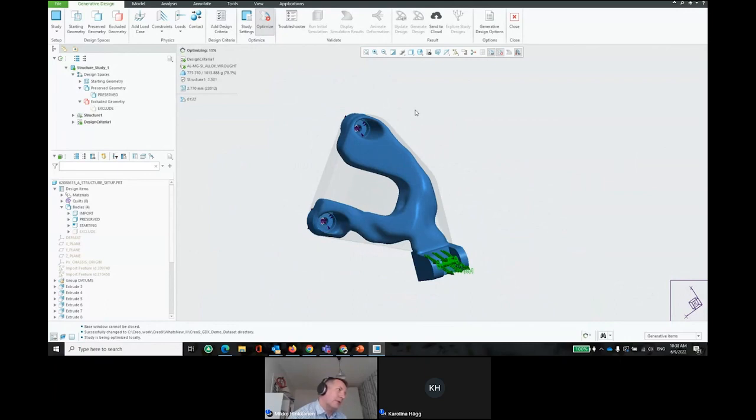And sometimes the results can be quite surprising, like, oh, you can do it like that as well. With enough limitations, you can do things like sheet metal parts or something like that. And sometimes it's good to understand that this is not necessarily manufacturable geometry as is, but you can still use it as a base for designing your own component and consider the manufacturing limitations while you design. You just get the overall shape with this generative topology optimization.